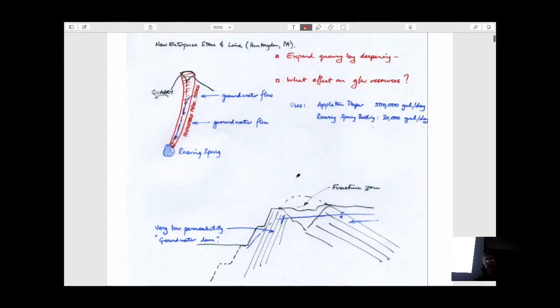And so if you can imagine it in this perspective, this is the same fold, is that within this fractured zone here, which is all busted up rock, it goes down on a lineament. And if you look at State College, the place where State College Borough gets all its water from are these fracture zones that intersect each other. You put the well at the intersection, completely busted up. It sucks water into the fracture zone from the big volume around it, and it's the most effective way of getting water out of the ground.